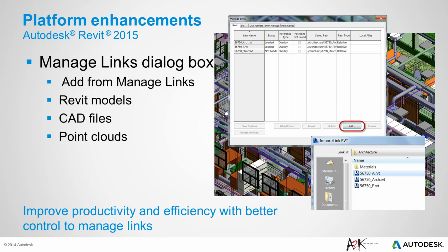Now multiple Revit, CAD and point cloud links can be added directly in the Manage Links dialog. Use the new Add button to insert a new Revit, CAD or point cloud link directly from the Manage Links, and the file will automatically be placed.